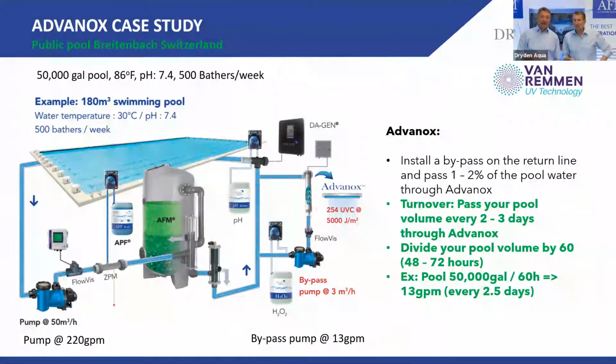Okay? Exactly. And how you do it, you install a bypass pump. So we install a bypass here, we install a bypass pump. Smallest pump that you find, you know, $200. Ideally also a flow meter. Not ideally, please do it, so you can control the flows.